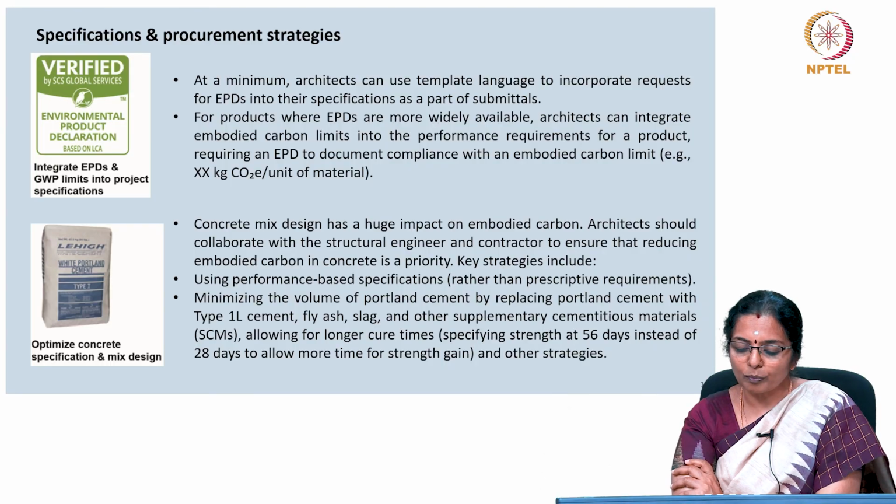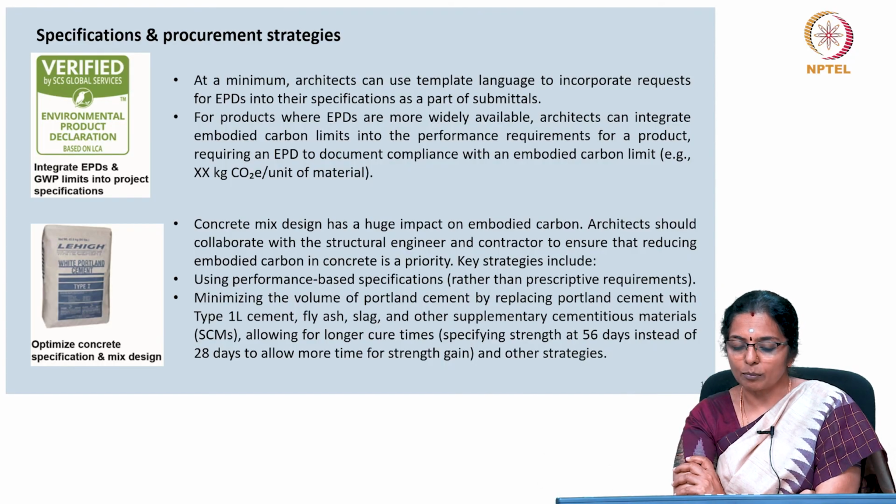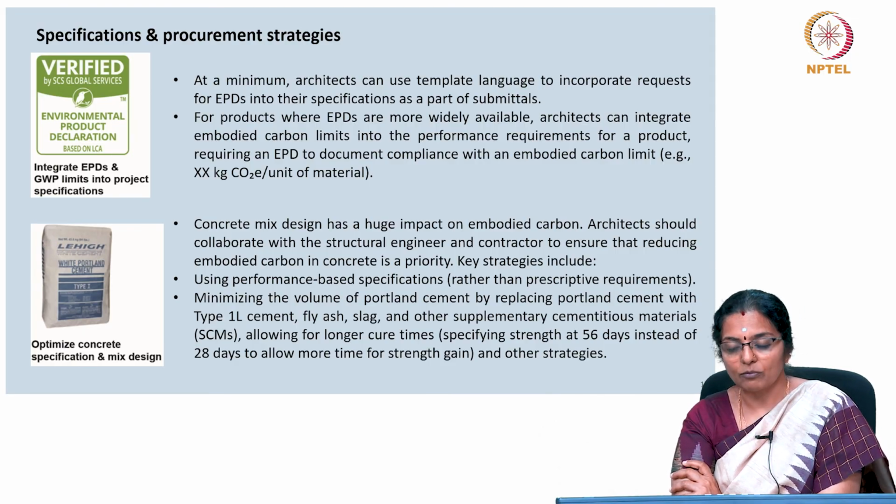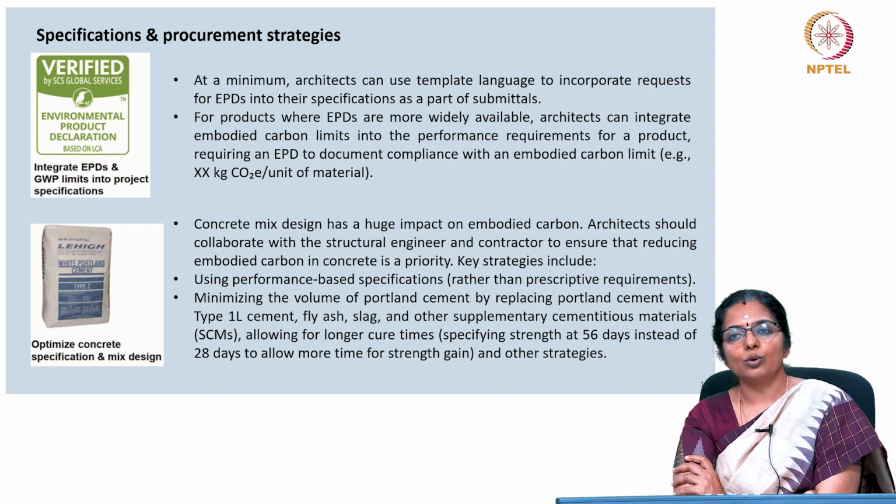Minimizing the volume of Portland cement by replacing Portland cement with type 1L cement, fly ash, slag and other supplementary cementitious material, allowing for longer cure times, specifying strength at 56 days instead of 28 days to allow more time for strength gain, and use other innovative strategies.